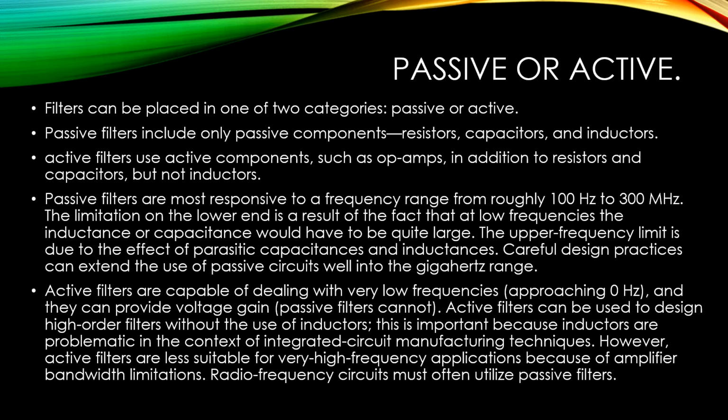Passive filters are most responsive to a frequency range from roughly 100 Hz to 300 MHz. The limitation on the lower end is a result of the fact that at low frequency the inductors or capacitors will have to be quite large. The upper frequency limit is due to the effect of parasitic capacitors and inductors. Careful design practice can extend the use of passive circuits well into the gigahertz range.